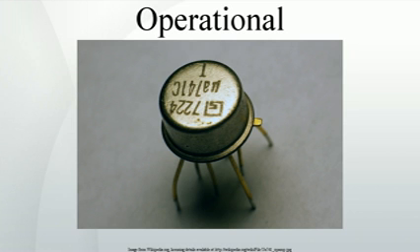A basic circuit is designed, often with the help of circuit modeling on a computer. Specific commercially available op-amps and other components are then chosen that meet the design criteria within the specified tolerances at acceptable cost. If not all criteria can be met, the specification may need to be modified. A prototype is then built and tested. Changes to meet or improve the specification, alter functionality, or reduce the cost may be made.